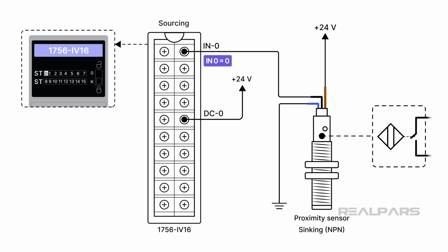If you decide to measure the input voltages for the on and off LED states, don't be fooled. They are the opposite of the sourcing sensor and sinking PLC input combination we discussed earlier. When the LED is on, the input voltage will be close to 0. When it is off, the input voltage will be about plus 24 volts.